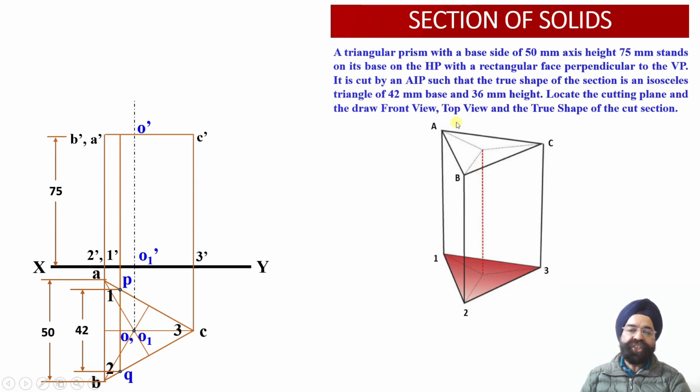From the front view projections, both of these 2 points will be overlapping with each other. So in the front view, this point will correspond to the 2 points of intersection P dash and Q dash of the 2 adjacent edges which have been cut by this auxiliary inclined plane over here. So this way, in the front view, we have been able to evaluate one point through which the auxiliary inclined plane should be passing. Here the starting point was from the plan projection view.